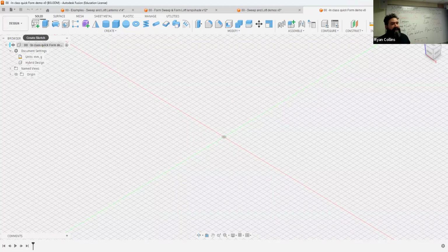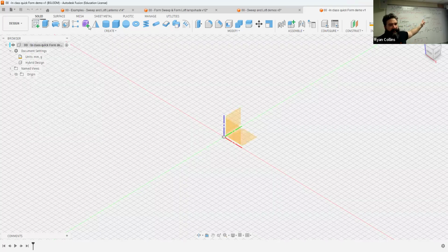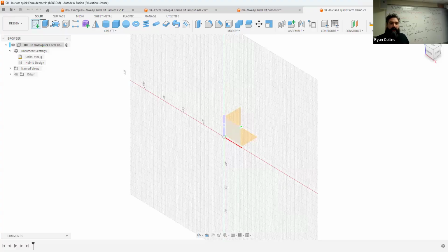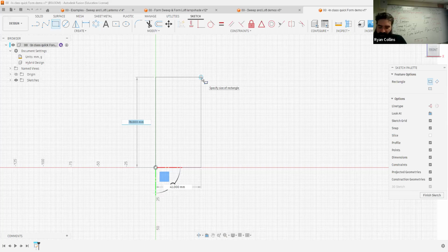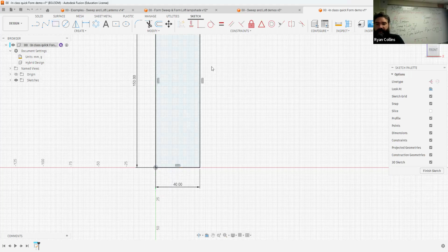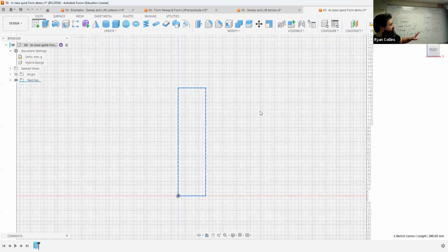If you wanted to base your design off of sketches and anything like that, perfect. I'm going to start a sketch simply to give myself a frame of reference because we're going to establish this project at a 150 by 60 millimeter wide reference point. Now remember, if I'm typing 150 to go up, width is radius, not diameter, radius. So I would need to type in like 30 for the width. You can make it a little bit bigger, that's okay, but don't go too crazy with that. And I'm going to double click that, turn it into a construction line. But that is absolutely just there for me to have a frame of reference.